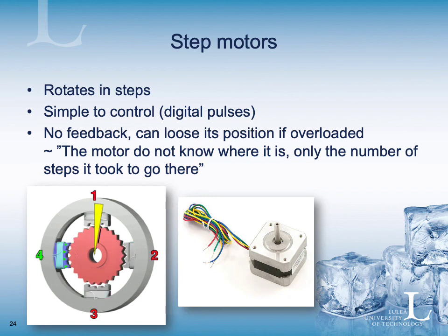For instance, if you have a car with electric gauges, you sometimes can see that when you start up the car, it goes from 0 to maximum to 0, which is normally a calibration sequence for the step motor in, for instance, the RPM gauge. This also looks cool maybe for the user, but the main reason why they do it is to calibrate the step motor.